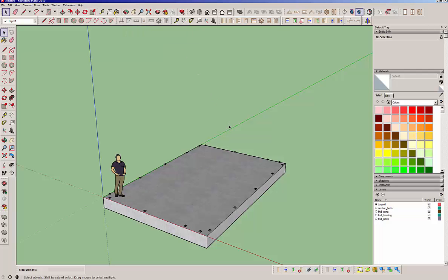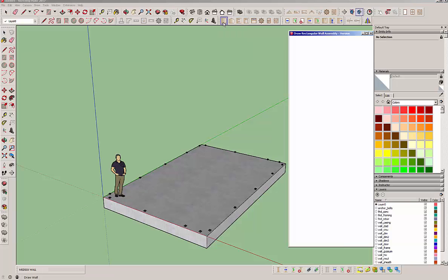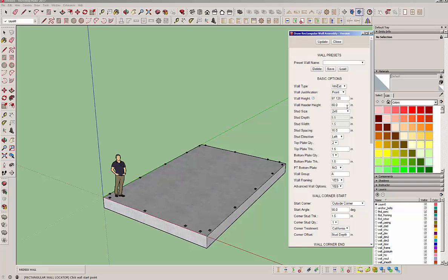And so first of all, we lay down a foundation, and I usually like to start, just like you build any structure in real life, you start from the bottom and you work your way toward the top. That seems to work reasonably well as far as workflow goes. Next thing I'll do is I'm going to put 4 walls up. So we'll go ahead and draw walls, and in this case I want to do a 10-foot wall.